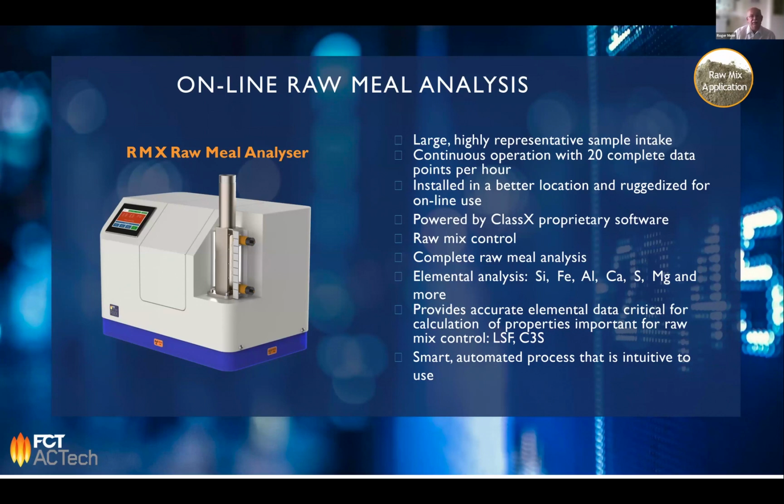The whole machine is fully automated, which means, and this is the big difference of our approach with all lab approaches, the material goes into the analyzer directly from the sampler via this tube. And there we have sensors to steer the process of the sampling. And we have always fresh material in the analyzer. Then the material passes the analyzer, and after the measurement, it can leave the analyzer, either being returned to the process, or fractions of the sample can also be kept for further analysis in the lab or for other tests like the physical tests, etc.